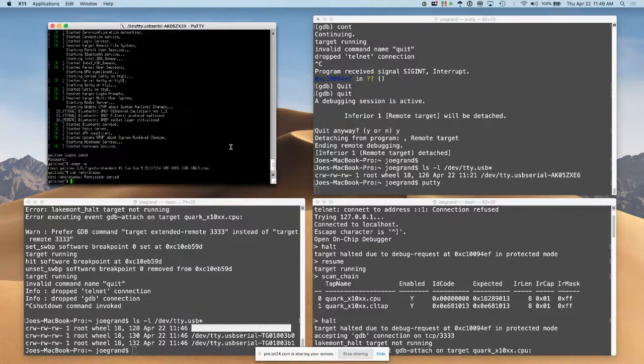So we can try to read the shadow file, permission denied. We can't because we are a normal user. And now we can use the magic of JTAG to connect up, patch that access control check, patch that function that's checking to see if we have permission, and then let us read it. So let's see how fast I can do this one. All right, so now we're in.